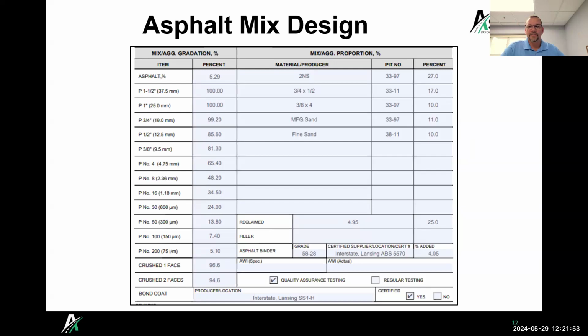A good example is where MDOT has what they call high stress areas. If you've got a mix design for a 5E ML or something, and then for a short stretch you've got to switch the liquid over for the high stress application, that's a simple change to your mix design, not having to go through a whole new process. Good to know, especially with our supply chain, which can sometimes make a difference in what's available to us.